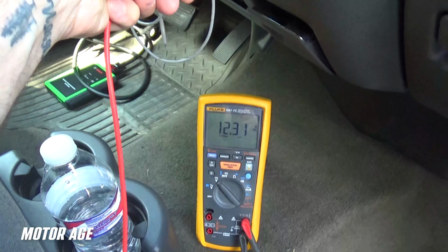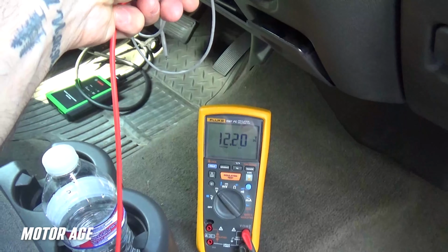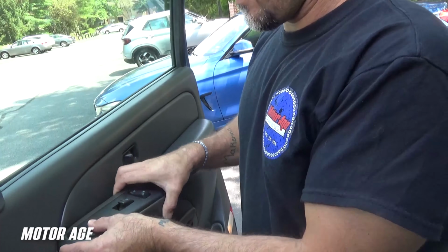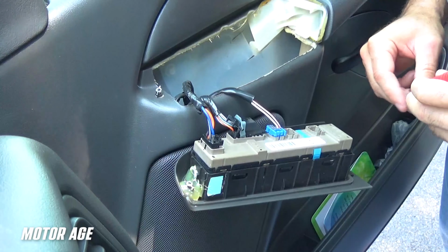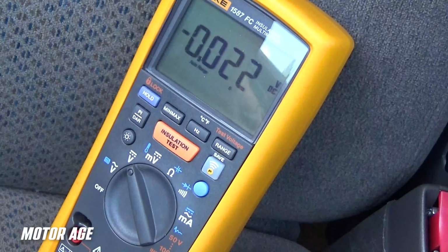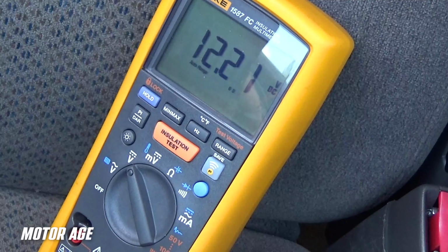And as we can see, near battery voltage is present. We know we can trust our equipment and its connections. And now we're going to gain access to the connector so we can verify we've got proper voltage and ground feed where it's supposed to be when we operate the power window switch in the down position. So first we're going to check the orange wire, which is our voltage source wire. And there we have it. So voltage is available. Now we know voltage is available to the switch.